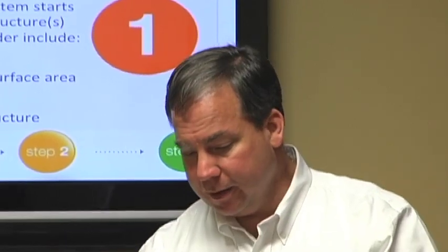We will do continuity testing on some structures. That seawall I showed, those are generally individual segments of sheet that are piled, driven into the ground and connected. Well, you want to make sure those connections are electrical. So we'll actually go out and test to make sure there's electrical continuity. There again, it's pretty easy to bond across them. So there's some issues there. We want to know what metal it is. Remember I mentioned there's some metals that you don't want to put too much light onto because you can damage them. So we want to know what metal it is. Carbon steel, is there copper in the area? Or do we have to worry about copper? So there's a lot of questions we'll ask about the structure we're trying to protect.